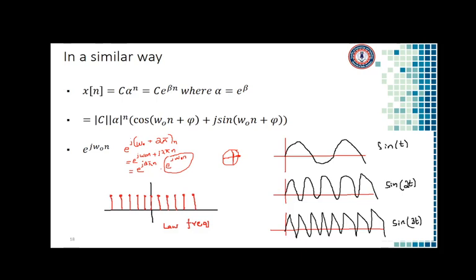So the question arises: what is the highest frequency then? What is the highest frequency I can get? Well, the highest frequency you can get is flipping back as fast as you can go, and that's simply this signal. This is about as fast as I can make a digital sinusoid, and this corresponds to omega equals π.